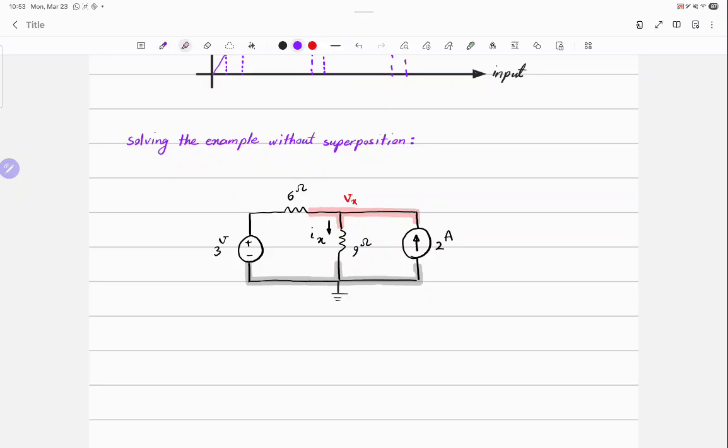And how about that one? What should I call that? Should I give it a label or no? Just 3. It's not an unknown. Do you all see that? Do you see the battery connected between ground and that node? So it's not even an unknown. So technically, how many unknowns do you have if you go for nodes? Only one, Vx. So that's not very bad actually.